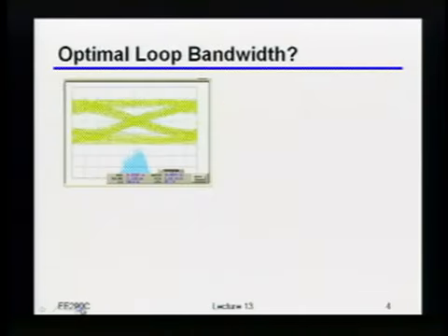Well, from that standpoint, the news is actually pretty bad, okay? Because if you remember, we talked a whole lot about the eye diagram that I would typically get, right? In this one, let's even assume that I equalized it. Well, even though I might have equalized this particular eye diagram, if I only did a symbol-spaced equalizer, then on the edges, I really have no idea what's going on, right?